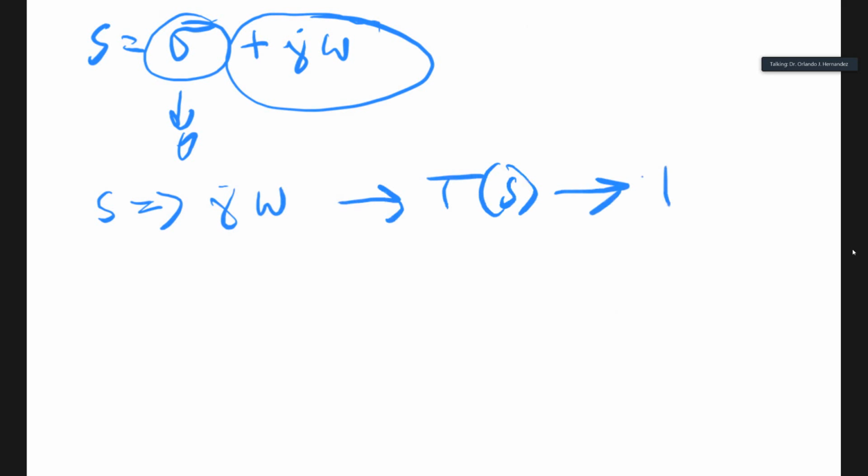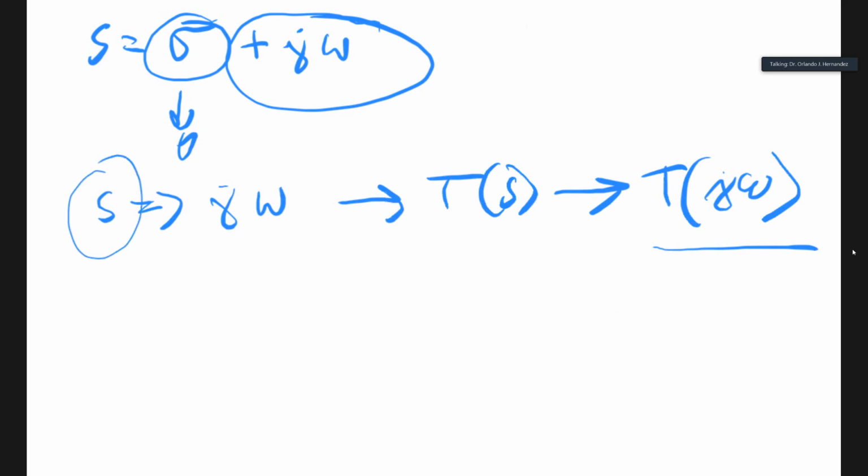So we set S to j omega, and we get a frequency response. That is the steady state, what we care about. When we are looking at this frequency response, we're not looking at the transient behavior. We have put that aside. We already checked out the system from a unit step response and stability perspective. We check all that in the S domain. And then we say, well, all that is good. Now let's look at the steady state response, and we get this transfer function on j omega, which is really the Fourier transform. The Fourier transform is a special case of the Laplace transform when sigma is equal to 0.